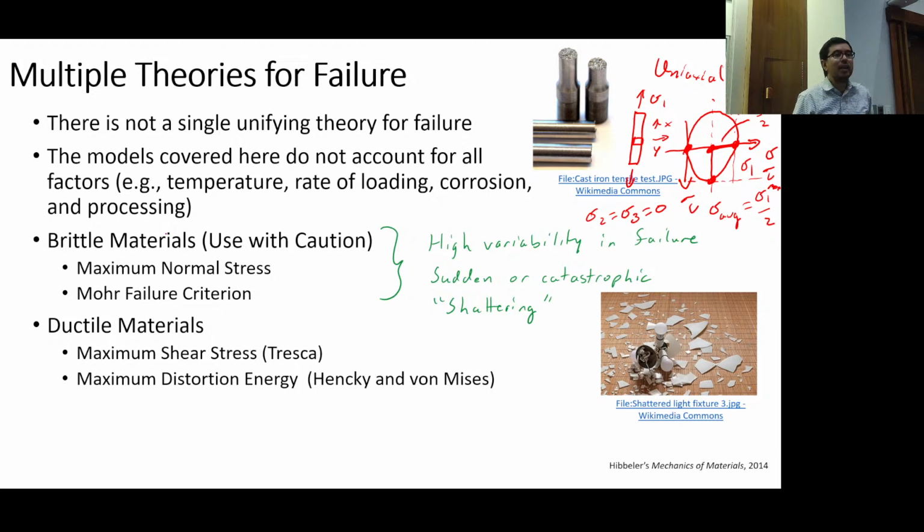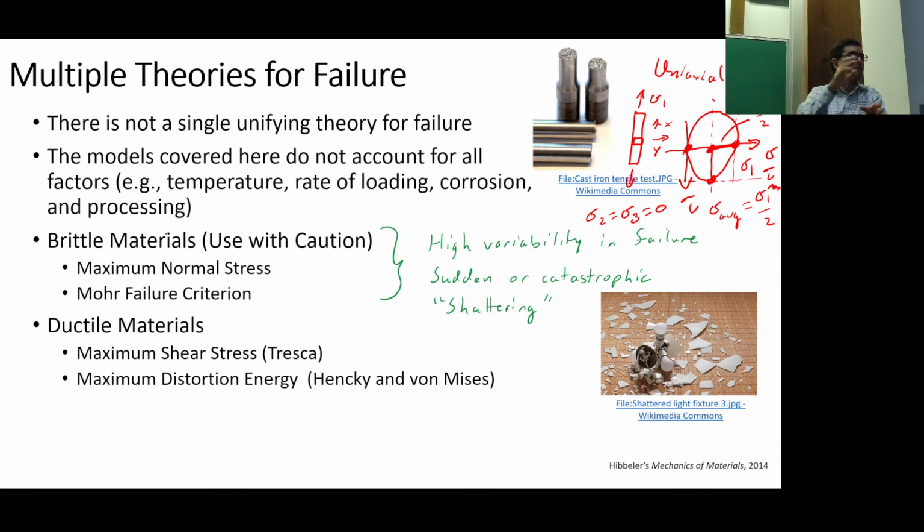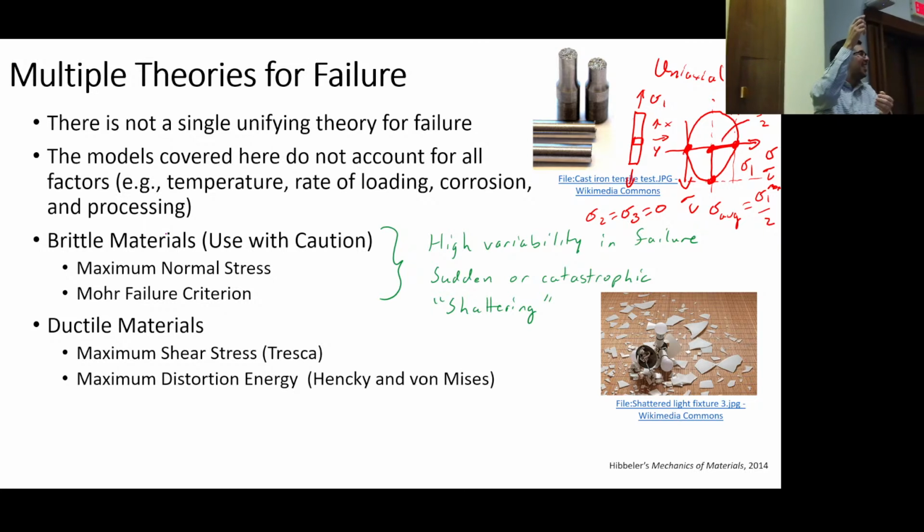So the maximum load, remember we have the linear elastic, perfectly plastic models, and remember that we only care about the elastic regime. For our intents and purposes, the elastic limit, the proportional limit, and the yield strength are all the same. We're not going to get into too much detail on the difference of these three. So the maximum stress that the material can handle under uniaxial loading, and uni means one, axis, in the Latin,